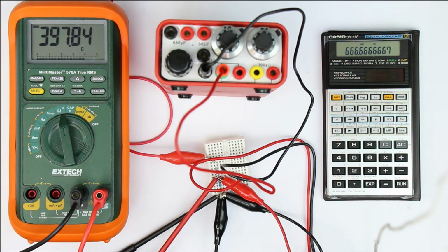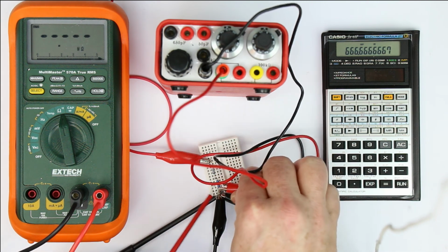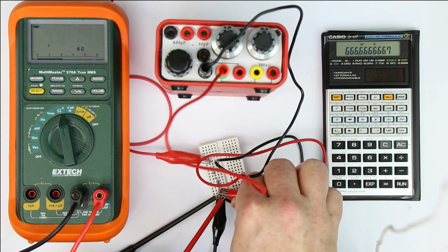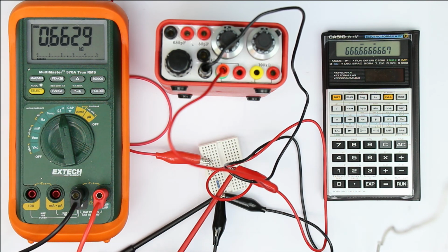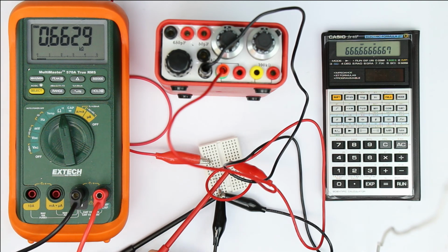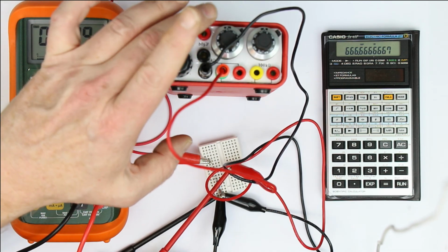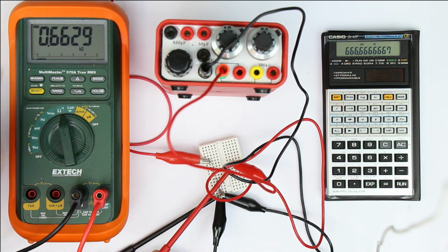Now let's measure the true resistance by disconnecting the power and going to ohms measurement, and again disconnecting these two connections so that we only measure the resistor box. And we get 0.663 kilo ohm, which is 663 ohms. So that's near enough to the theory. The inaccuracy is of course due to the fact that I cannot exactly set the values. So it's exactly what we expected.